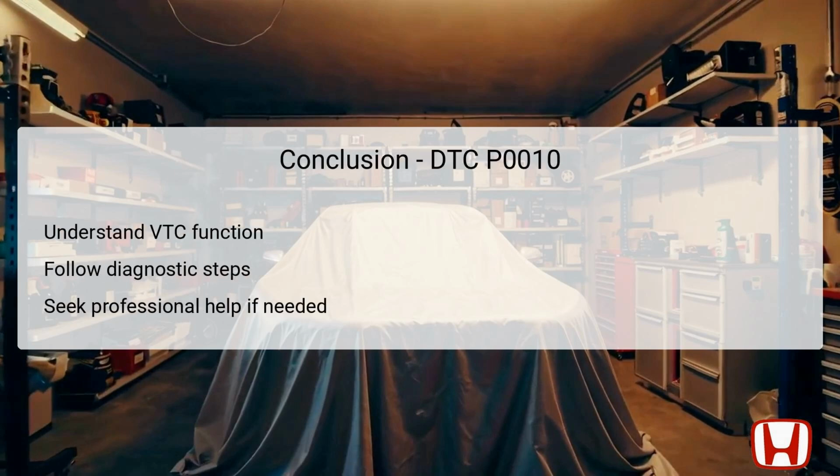In conclusion, understanding the VTC oil control solenoid valve's role in engine performance is essential for effective troubleshooting of DTC P0010. Following the outlined diagnostic steps ensures a systematic approach to identifying the problem accurately, whether it requires checking for resistance, continuity, or addressing wiring issues.